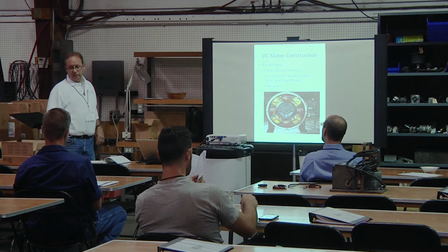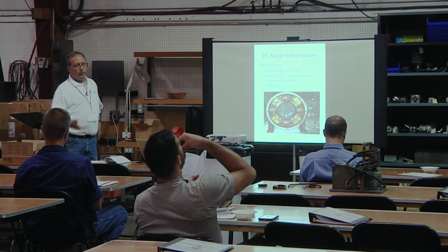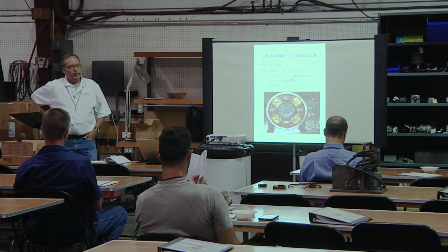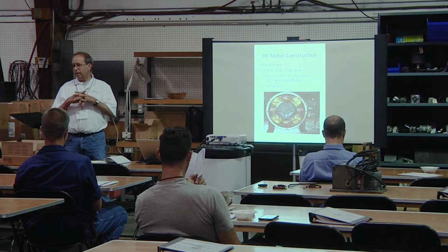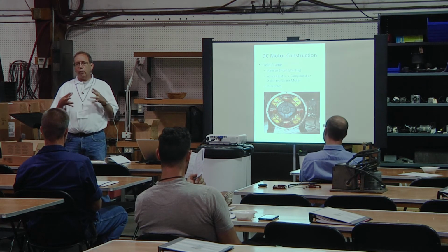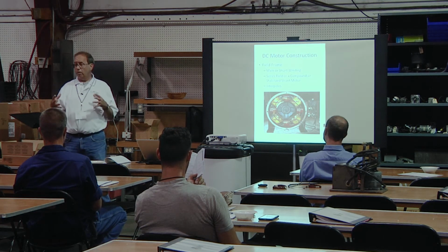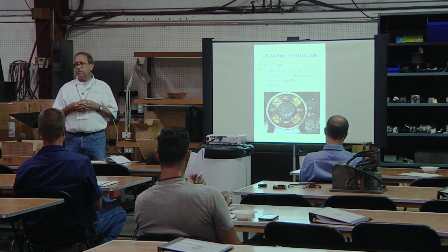Series wound DC motors, I can talk about that for a minute. Essentially, with a series wound motor, you get a lot of torque in a small package. You can't regulate the speed on them at all. The speed is totally load dependent. The more load you put on it, the slower it goes.